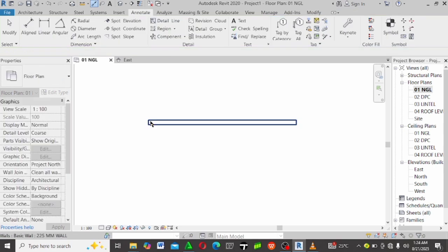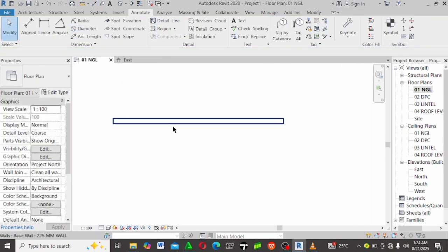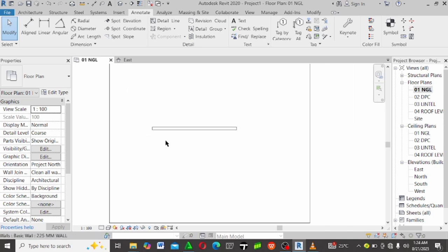All right. So another thing we have to know in Revit before drafting our walls is we have to set constraints. So what are constraints? Constraints are where the wall starts, where the component, anything you are importing in Revit. Constraints are where the thing is going to the base level. So we have base constraint and we have top constraint.